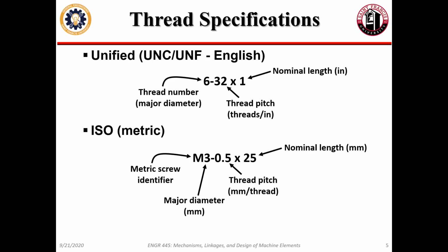How exactly do you measure? You pick one and you count from there. Your measurement will usually be plus or minus 1. So this is actually, I think, a 3/8 12. Yeah, pretty much. So this is a 3/8 12 screw.